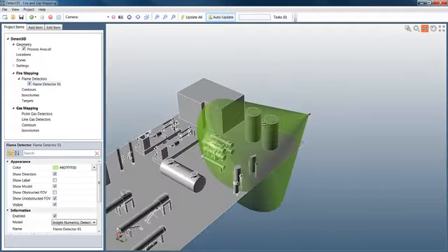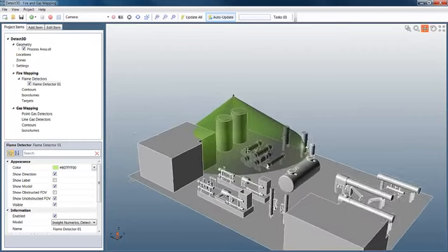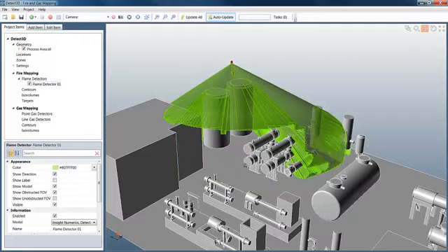Many of you are now familiar with our raycasting engine, which calculates what the flame detector can actually see. Just like you and me, visual flame detectors can't see through things, and in Detect3D, the flame detector can't see past the obstructions in the CAD file. I can show you that here. We call this the obstructed field of view.